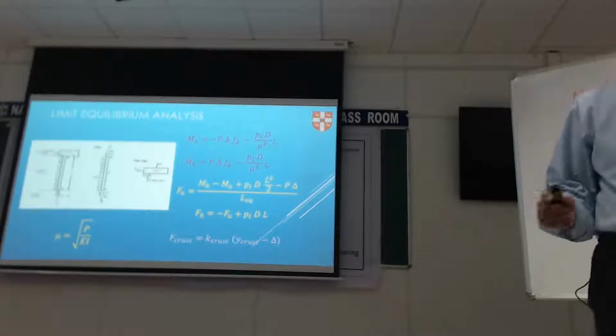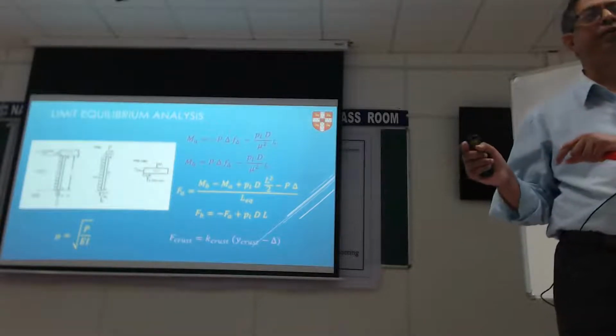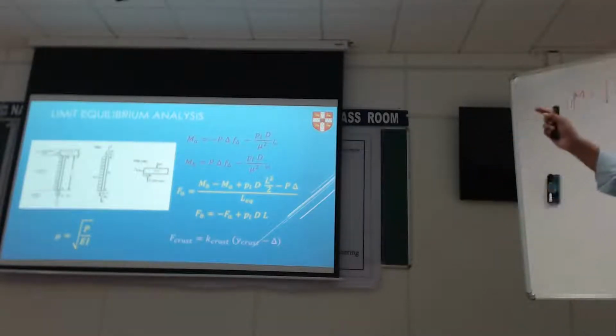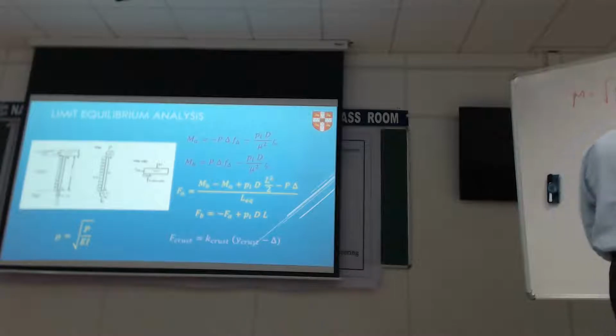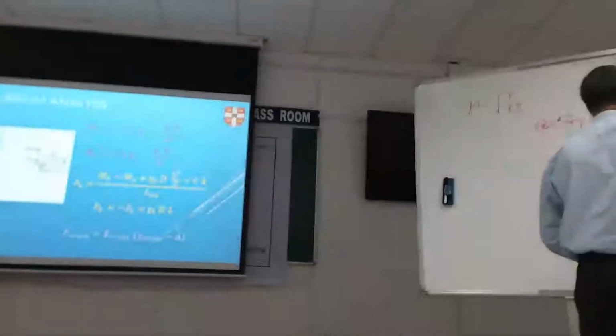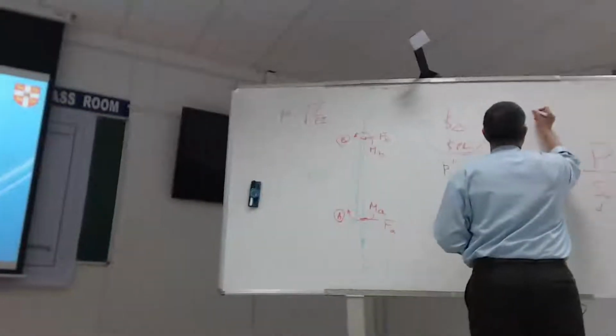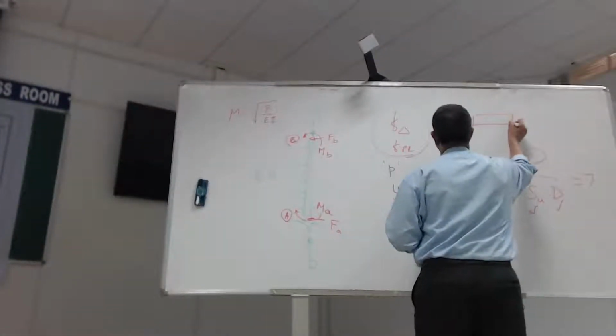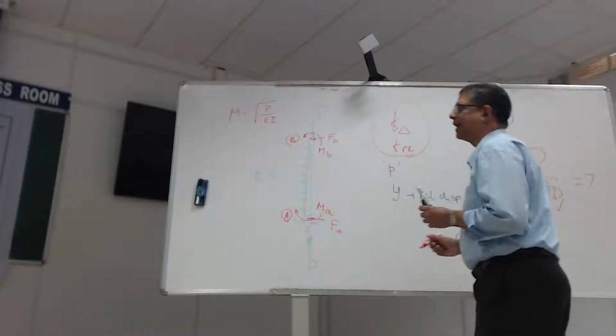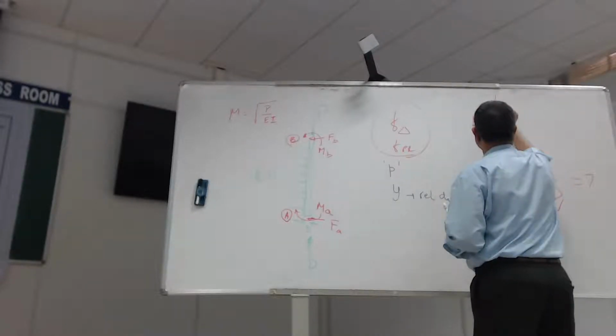What about the pile cap, which is sitting in the non-liquefiable crust? If it is sitting in a non-liquefiable crust, and I draw the free body diagram for that, I'm going to get the forces on the pile cap.